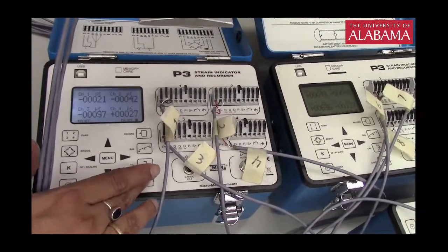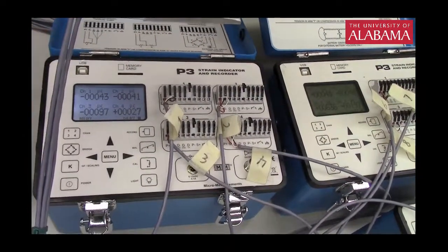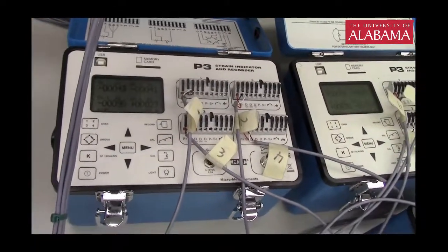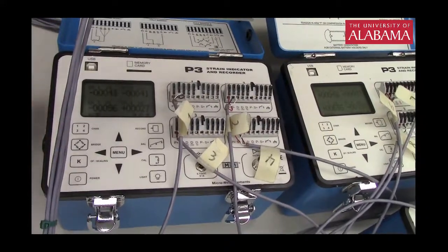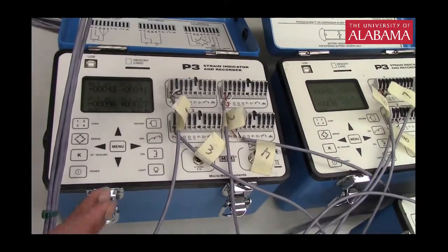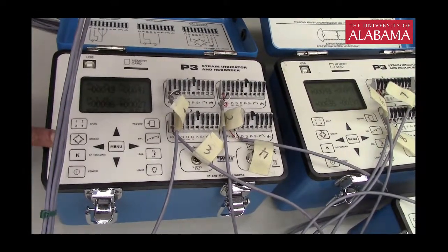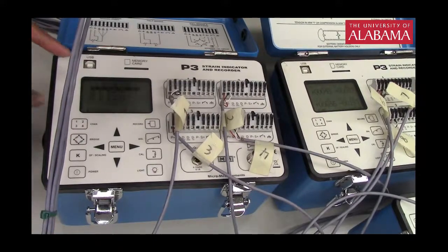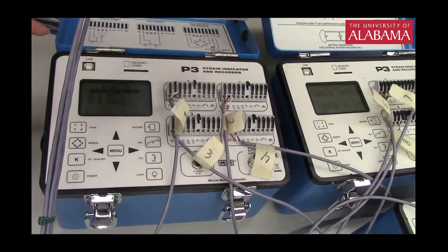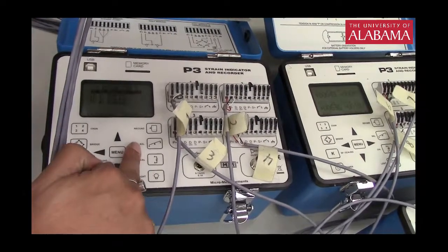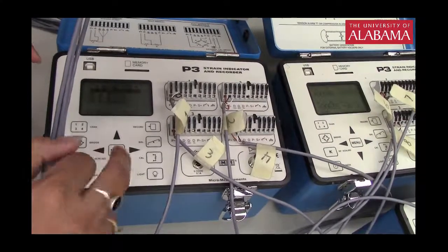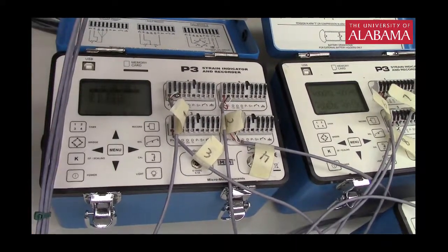So let me first press on the first box, and we can see that the box gives me garbage value, although there is no load right now. So firstly I'm going to check whether the box has proper gauge factor and has a proper bridge type. The very first thing which I'm going to do is press the bridge button, and you can see that all the channels are quarter. Okay, so we need quarter gauge for this experiment. If you press this button, it moves to other types of bridges, but we won't worry about that. We will just make sure that it's quarter.